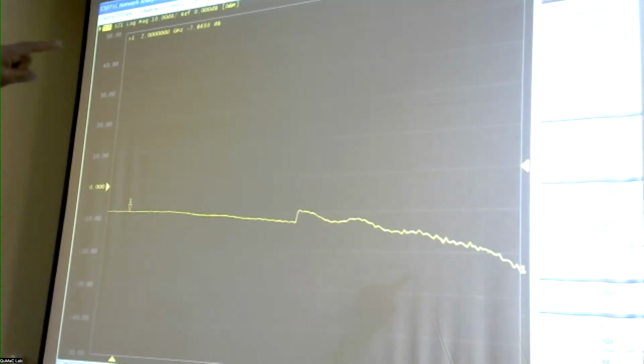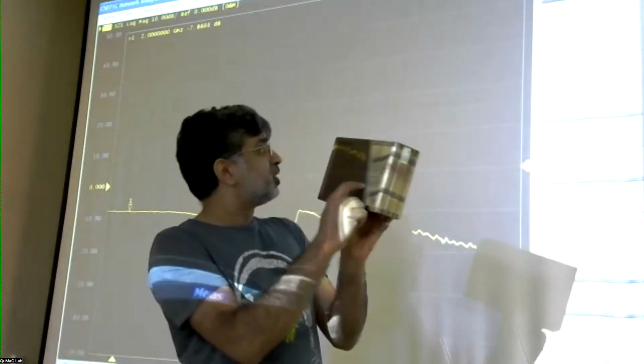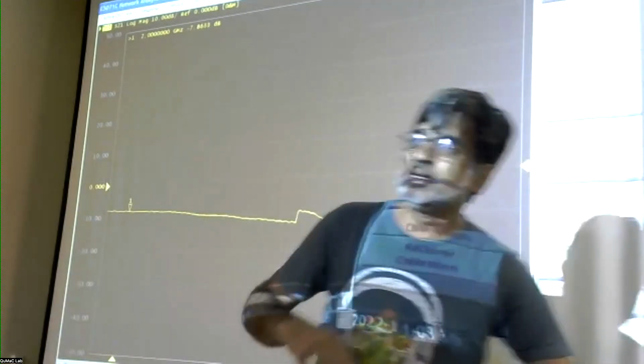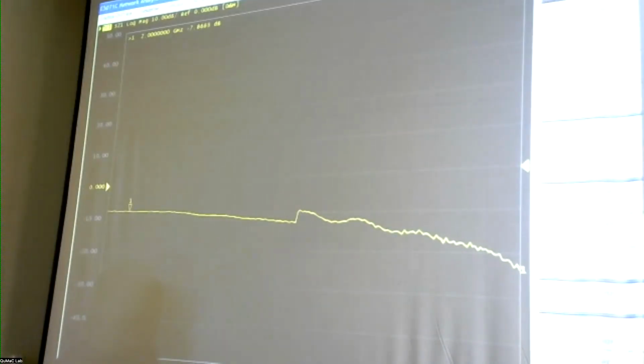Right now it says correction off because there is no such correction being done, but there are methods here, and it also has this thing called calkit, and it gives a number there. That number usually has to match the number which is written on this box. So it's actually not the same one. This one is 85052D. That way it knows which data, and in earlier days it used to come with a disk and you can even upload the data onto this.